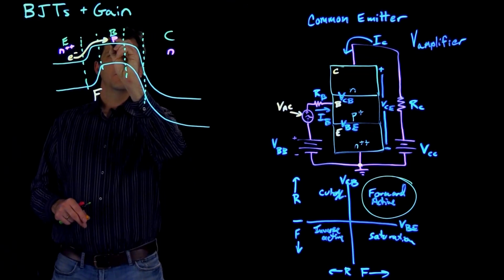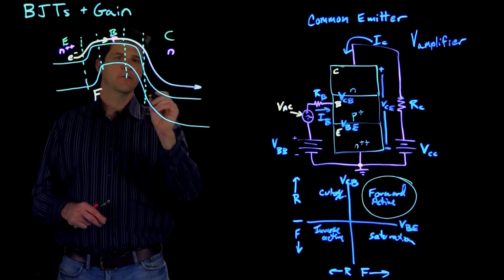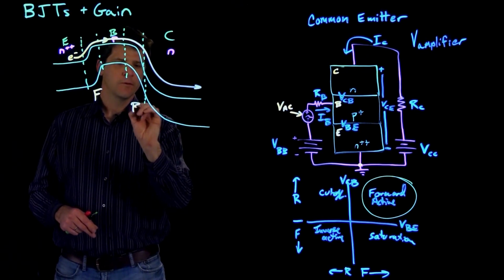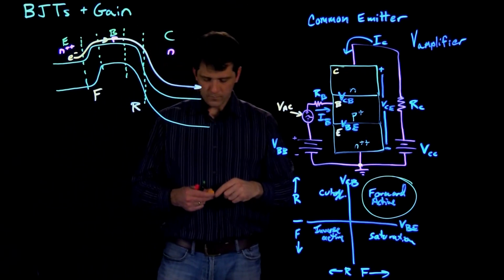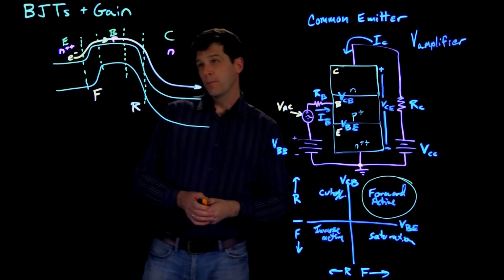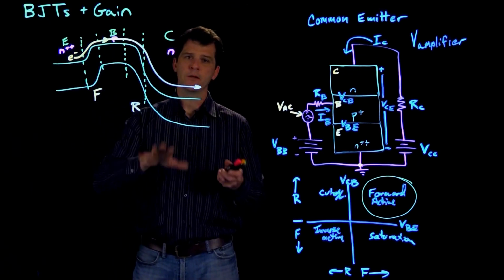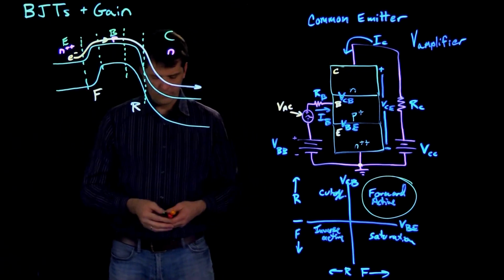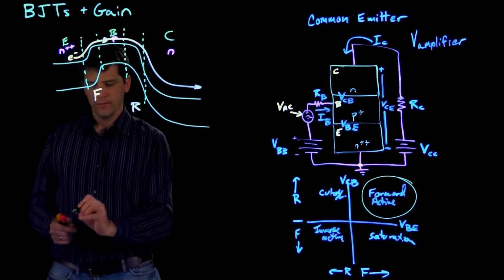And then what we want is for all of them to be swept through and out of the device. So this one is in reverse bias to help with that collection. So we can envision the travel of a single electron here, but really to understand what's going on, we need to look at the minority carrier distributions.